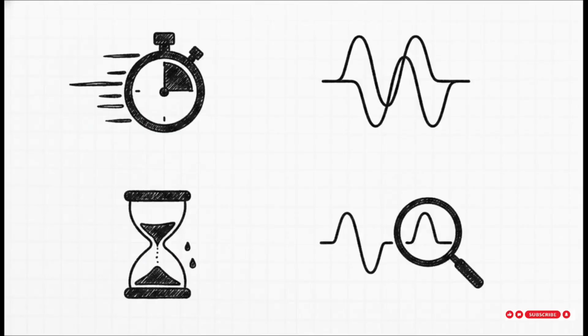When we evaluate dynamic instruments, we grade them on these 4 main traits. We want a high speed of response, meaning it reacts rapidly. We want high fidelity, so it faithfully follows changes without distorting the signal. But we actively want to minimize lag, that annoying delay we just talked about, and dynamic error, which is the actual gap between reality and what the delayed dial is showing you.